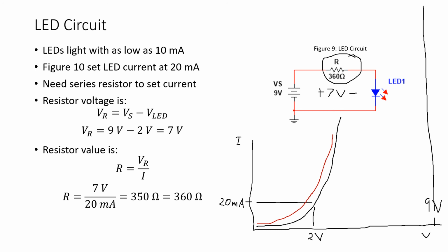the rectified waveform. And then we finished by looking at LEDs and discussed the fact that the color of an LED is determined by the dopants used in the semiconductor material, or the dopants added to the silicon in the semiconductor material. And then we finally looked at the design of a simple LED driving circuit where we select the value of the resistor R in series with the LED to limit the current through the LED.